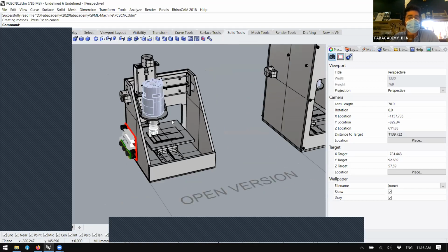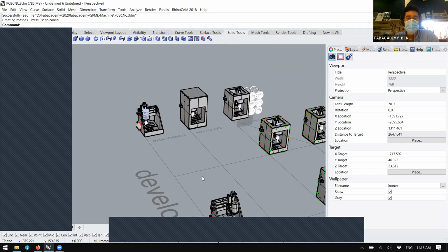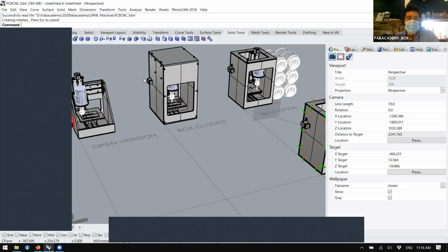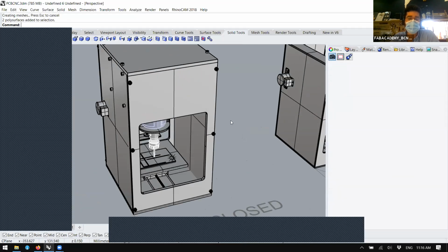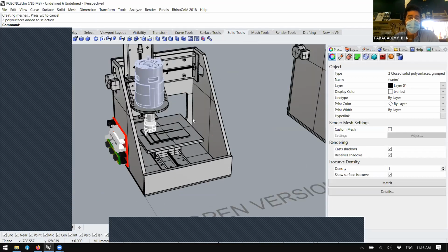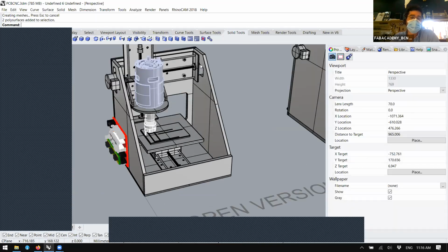A machine like this is easier to fix and modify if it's the first time you make a machine. So as we initially designed, let's say, the base frame, these screws are not correctly in place. We design what is the shape and the main location of the most important part. The most important part location is actually the rails. The first thing you want to design is, okay, how you want to move and how you are going to put the rails in the space.